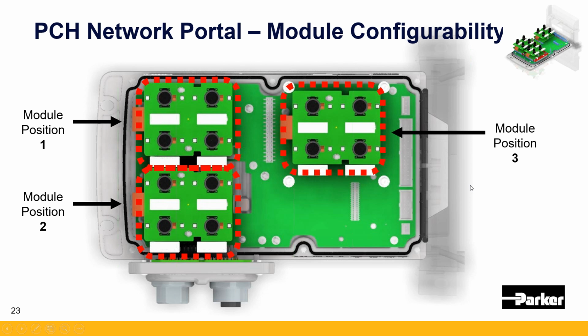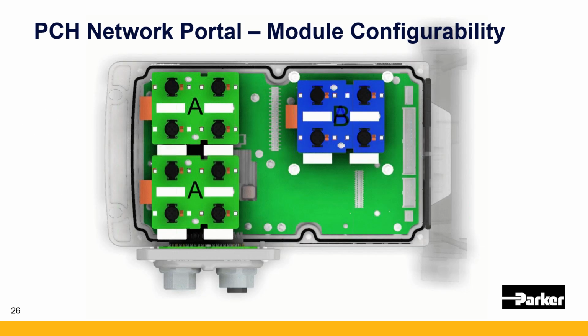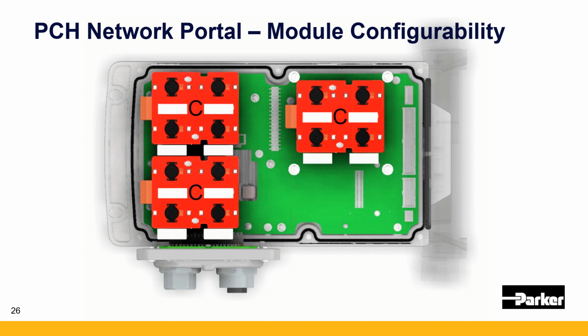Okay. Now we also have a C variant. Folks told us when we were designing, hey, the idea of doing configurable outputs is really cool, but sometimes we just need some dedicated Aux Power ports on there. So we went ahead and designed that in here. Those top two ports are fixed. They behave as 500 milliamp outputs on Aux Power. But the bottom two ports, what you're seeing on the bottom here, can each behave as an IO-Link Class B, one input or one output. This is kind of like that last module variant I showed you.